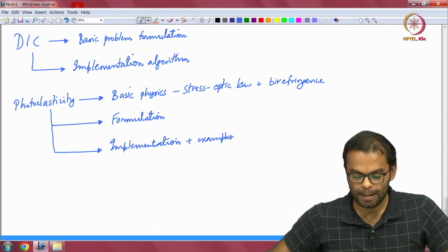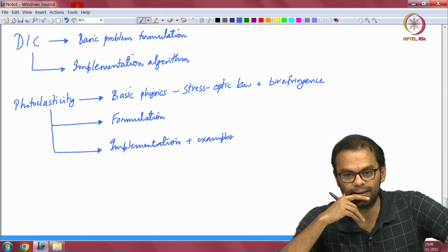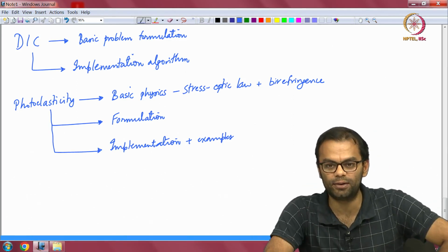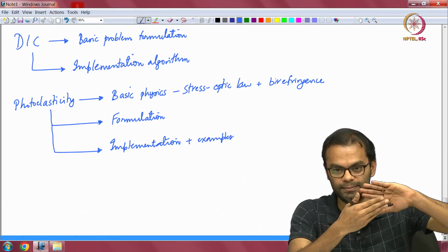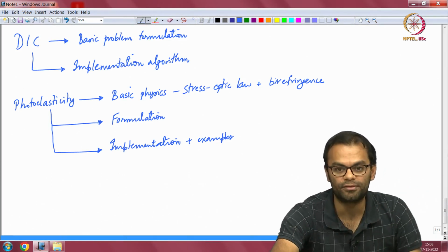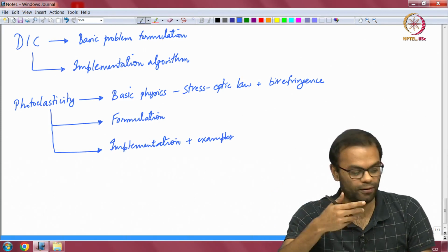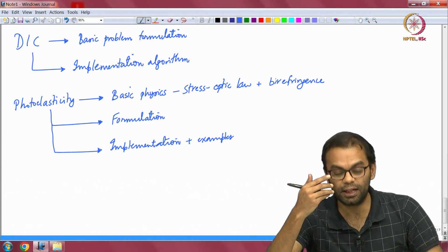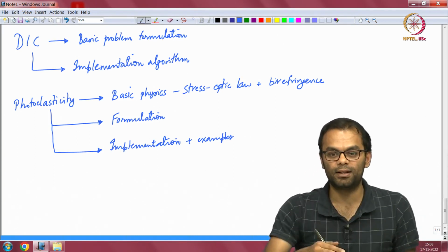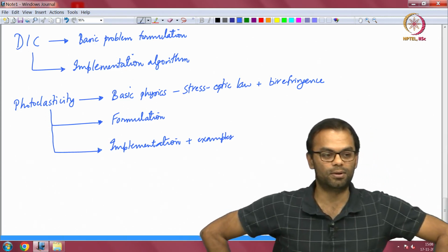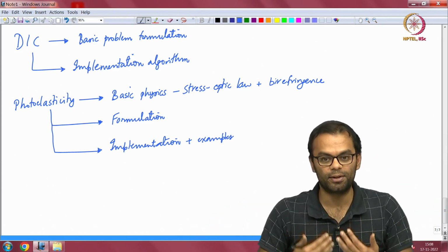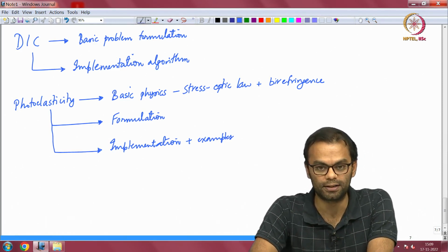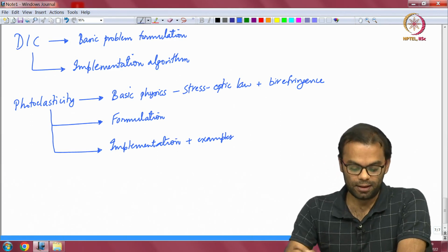You can actually see photoelasticity quite easily. You need what is called a polarizer sheet. You can take 2 polarizer sheets, cross them, and look through maybe any glass window near the ends. You can even look at a phone screen, for instance, and you will see colored fringes. Those fringes give you information about the stress in the system. In the case of the phone glass, the residual stress. You can extract quantitative information from those color fringes, and that is what hopefully you will be able to do after the second bit on photoelasticity.